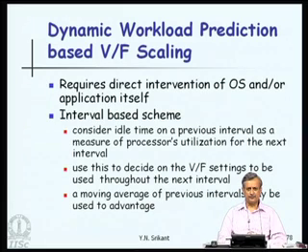If during this particular interval the CPU has not been working at its best, for example its activity factor is probably less, maybe 0.5, 0.4, 0.6, whatever, then it is possible that by running the CPU at a lower voltage and frequency during the next interval, we are going to save some energy, but at the same time stretch the activity factor to 1 and make sure that the program itself does not suffer in performance.